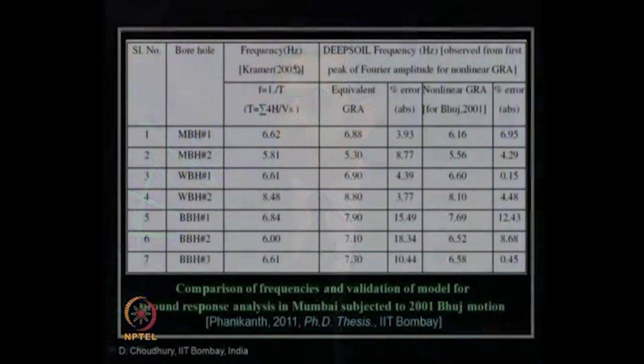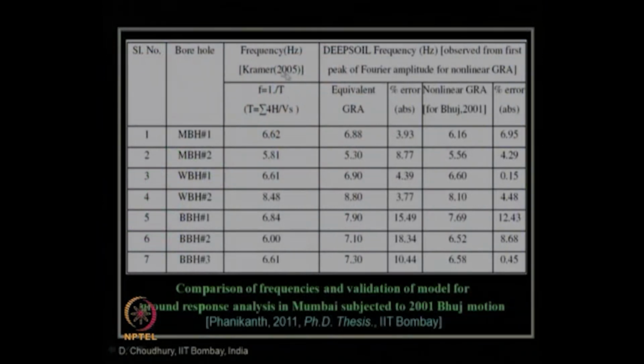We had also seen in our previous lecture that the frequency computed using this formula, which is a thumb rule as I have already mentioned for a typical homogeneous soil layer, that is the fundamental natural period, how to estimate from the Vs value compared to thickness of a soil layer, and what is the frequency obtained using this DEEPSOIL software, using either equivalent ground response analysis and non-equivalent or non-linear ground response analysis